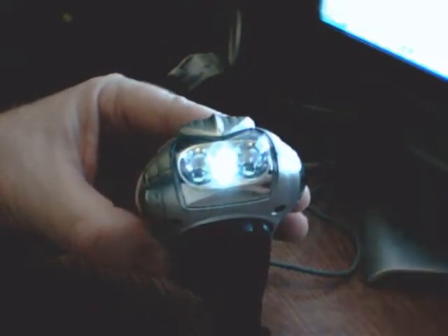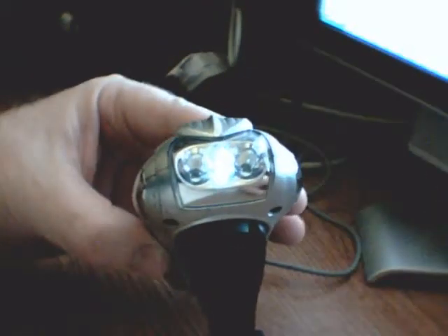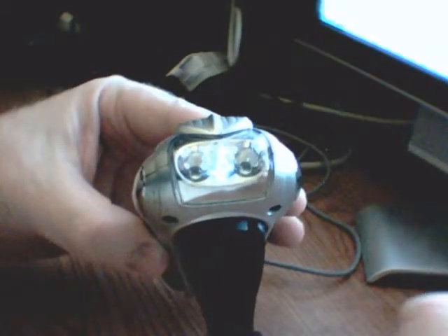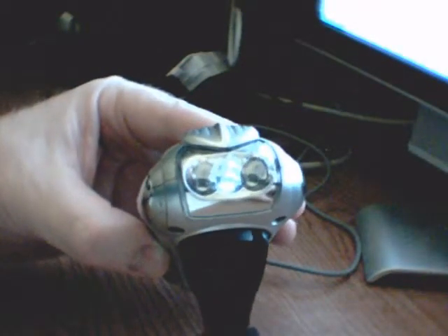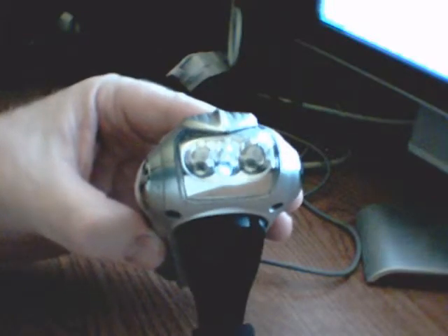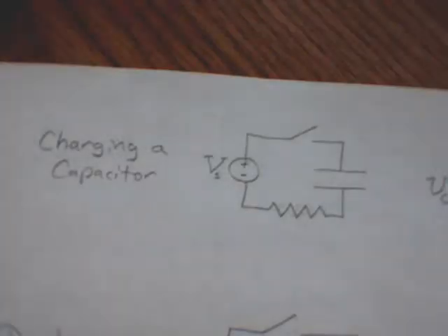We're going to see the brightness slowly start to climb and get higher and higher. And then once I quit charging the capacitor, you'll notice that there's this exponential decay in brightness. So it's really an exponential rise in brightness and an exponential decay in brightness that we can predict mathematically. The two things that video demonstrated is the charging and discharging of a capacitor.